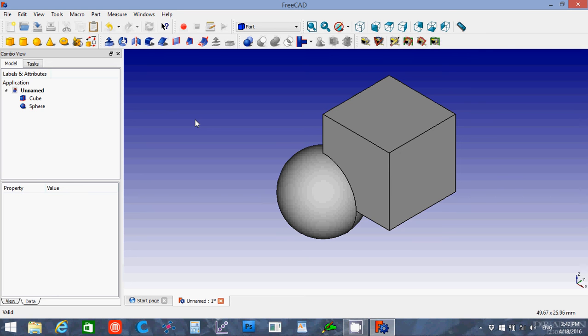So unless I'm in Part Design in the sketcher, it is useful to undo there, but it is highly unpredictable as far as the way it works when you're working in anything else. So I typically will just click on it and hit delete to undo the last task I did.